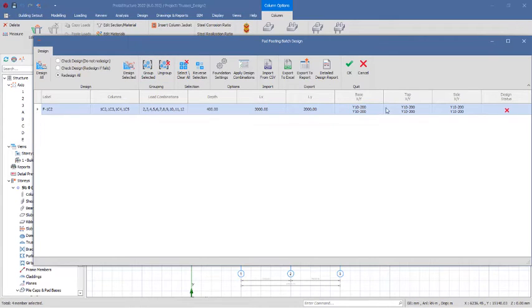Alright, so to consider a group design, you have to select the number of columns you need to actually add foundations to, just like this. Right click on it and then click on the insert pad footings. So once you click on insert pad footings, it is going to come up with a dialog just like this. Okay, so what you need to do here is you can group all of this to be one. If you want to group it, you need to select redesign all first, select the first one, hold the shift key, select the last one, so that you get all selected just like this. Then click on group these options.